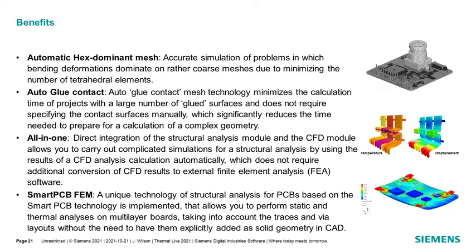So this uses this automatic hex dominant mesh, except for the smart PCB, which we looked at, which uses the triangular prism approach. FloEFD also uses auto glue contact, so there's very little setup time between setting up materials or areas that have different mesh. These are automatically glued together.